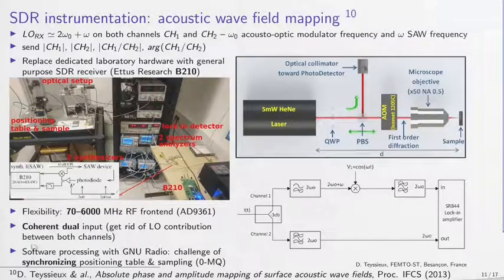So on the radio frequency step, what we would usually do is collect this optical signal that has been shifted by 2 times 80 megahertz, so that's 160 megahertz, plus the frequency of the vibrating sample here, the radio frequency sample that is being analyzed. And we wish to detect the phase and magnitude of this information. How do we detect this?